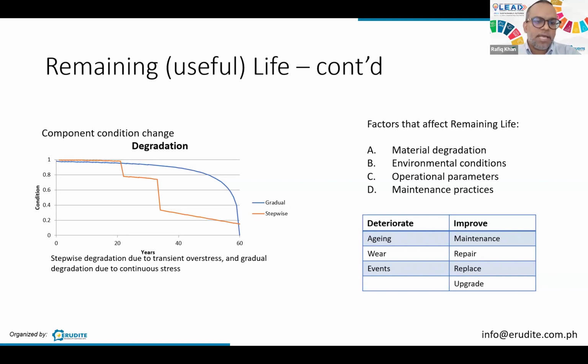insulation breakdown strength. Sudden changes in the insulation can also be a result of things like a flood that suddenly comes over a night, and then you have moisture ingress in the switchgear. Takes some time to dissipate out moisture, but then you see a stepwise degradation or reduction in breakdown voltage.